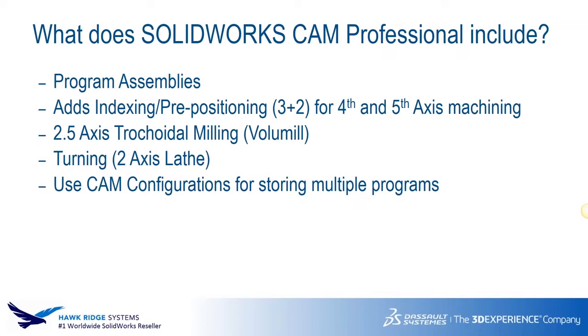As far as the post processors go, there are a bunch of posts included for a range of machines that are in the default installation files of 2018. You can also go and create your own post processors using a tool called the Universal Post Generator. Now that tool is available for download from the CamWorks website, as essentially where CamWorks and SOLIDWORKS CAM will be developed together. And also it comes with an NC editor.